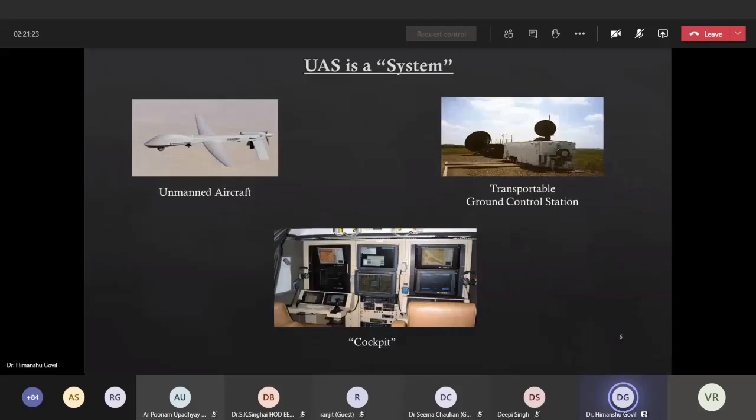So the aerial photographs you take by UAVs can come from a simple drone, a part of the UAVs, or a part of the systems. Systems are only required when we are doing a large survey in an area at a continent level rather than a local level. When we are working at a continent level, we have to go for a system because accuracy is more important to us, and we use this in terms of GPS location or in DGPS mode, RTK mode.